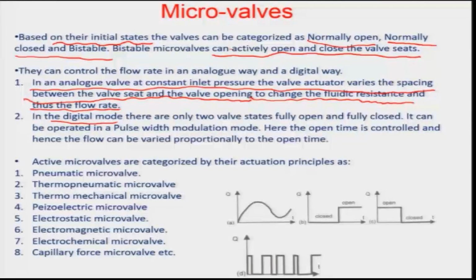So it can be operated in a pulse width modulation mode, where there is either an open position for the valve or a closed position, with as little time delay as possible between the open and the closed positions. Here of course the open time is controlled and hence the flow can be varied proportionally.